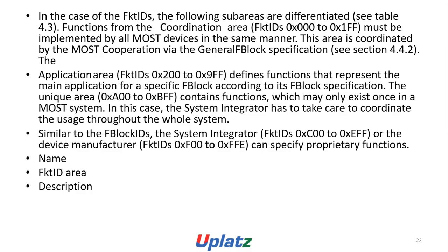In this case, the system integrator has to take care to coordinate the usage throughout the whole system, similar to the FBlock IDs. The system integrator, FktIDs 0xC00 to 0xEFF, or the device manufacturer, FktIDs 0xF00 to 0xFFE, can specify proprietary functions.